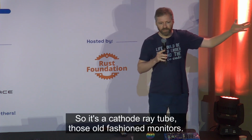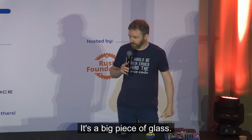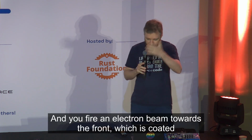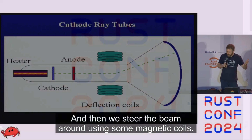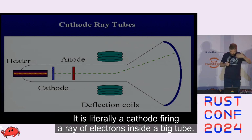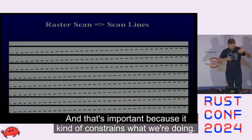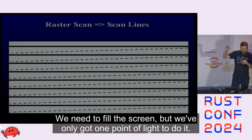So it's a cathode ray tube, those old-fashioned monitors. It's a big piece of glass, it's a vacuum inside, and you fire an electron beam towards the front, which is coated in a material that will fluoresce, and then we steer the beam around using some magnetic coils. It is literally a cathode firing a ray of electrons inside a big tube. And that's important because it kind of constrains what we're doing. We need to fill the screen, but we've only got one point of light to do it.